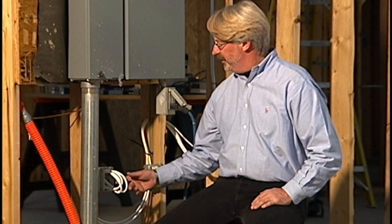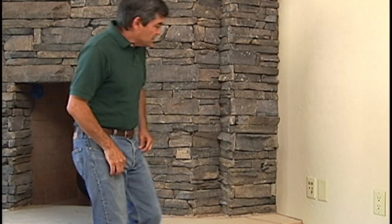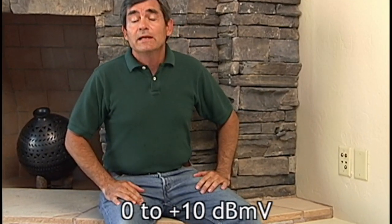The cable company's visual signal level at the NID or connection point at the house should not be anything less than plus 3 dBmV on any channel. Now, the signal level in the house at the point of connection of the customer's equipment should not be less than 0 dBmV on any channel.